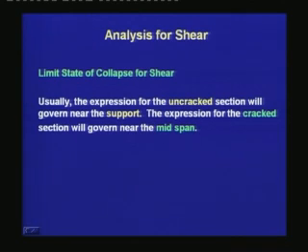Usually, the expression for the uncracked section will govern near the support. The expression for the cracked section will govern near the midspan.